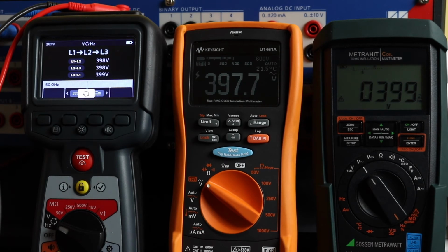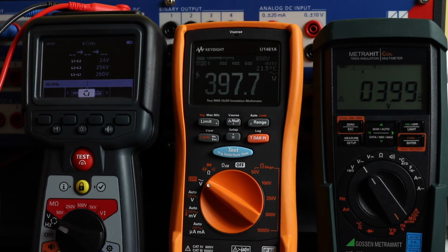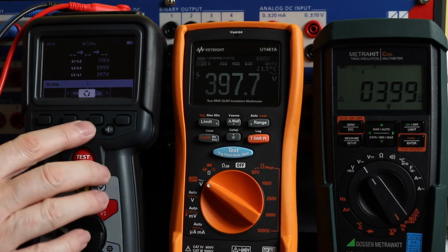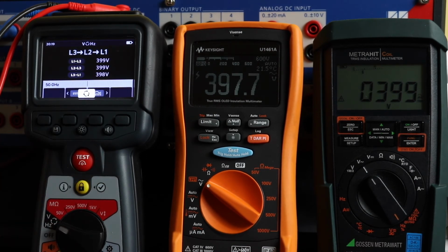There it is. At the top of the screen you've got the phase rotation as well. If I change over two of the leads you'll see the voltage drop off anyway. And put the light back on. And there you can see phase rotation has changed and all three voltage measurements are back. That three-phase rotation does come into its own with another function of the MTR105 as well for validating three-phase motor rotation, which we'll get into in another video.